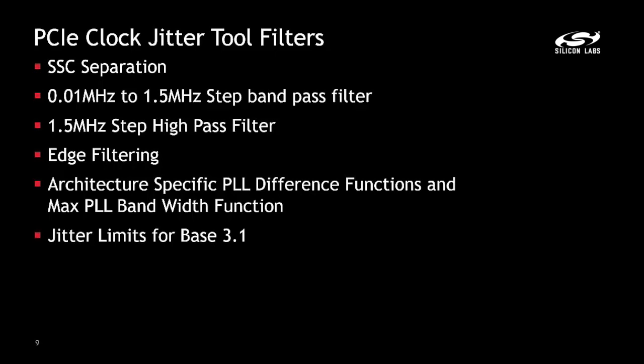PLL difference function and max PLL bandwidth function are applied to the reference clock's data, since the intent of the jitter measurements for the PCI Express reference clocks is to determine what the jitter is that is seen by the data latch at the CDR. Clock jitter at this latch will directly impact how much margin the CDR has to the incoming degraded data stream.